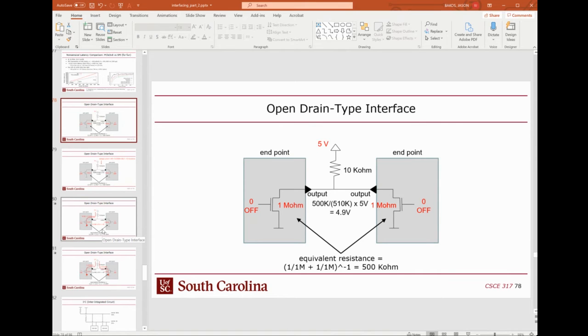And so, what's really going on? What is the advantage here? The advantage here is that the pull-up resistor ensures that you can never sink a whole lot of current, because you've got a resistor that's in series with the power supply.